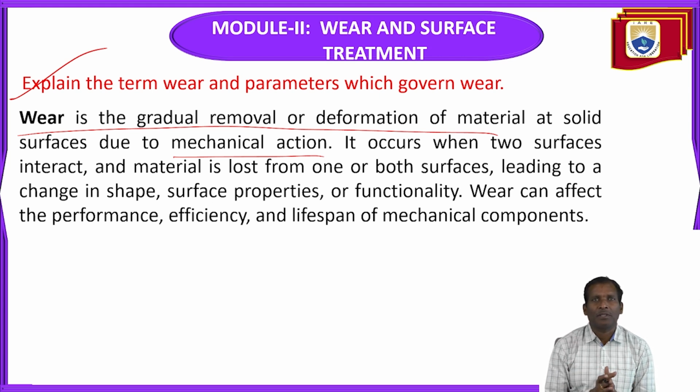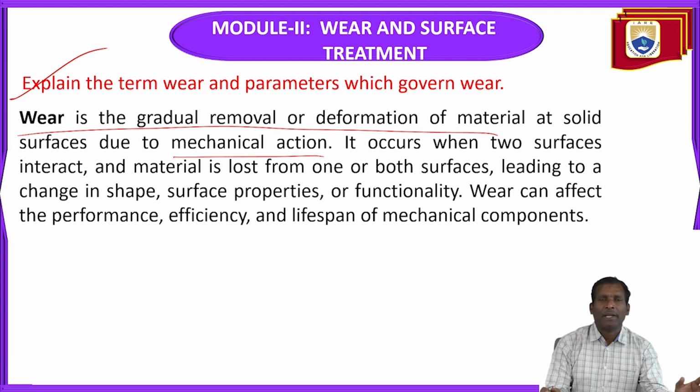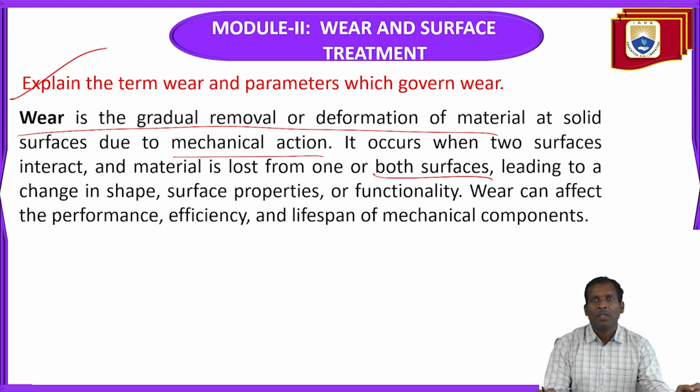due to poor surface finish, due to stress concentration properties, and due to the presence of foreign materials on the surface. So various factors are there for removal or deformation of material from the surface. It occurs when two surfaces interact, and material is lost from one or both surfaces. It may be one surface or both surfaces, material will be lost. This leads to a change in shape, surface properties or functionality.